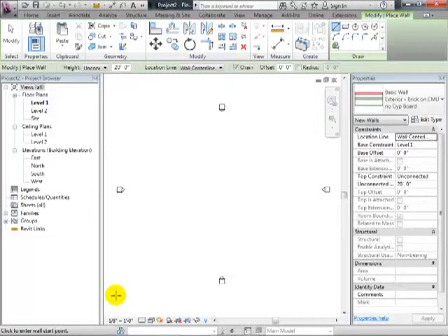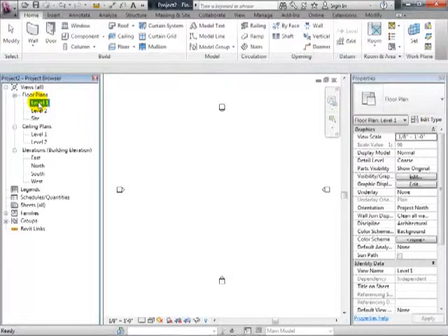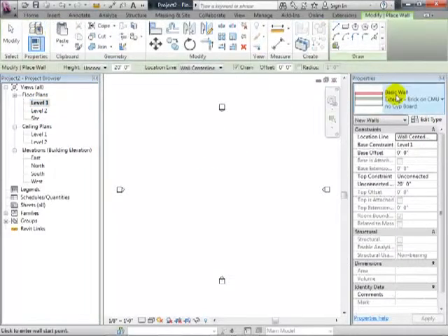Okay, so when you go ahead and put walls in, let's think about just basic wall modeling. If we start placing walls, I'm going to place the wall on level 1, but I'll make it a little bit tall. Choose your basic wall type. You get to say what the height of the wall is, whether it's 20 feet unconnected or up to a specific floor level. Ultimately, you're probably going to do things to specific floor levels. That's really a stronger way to do it. For now, I'm just going to leave it unconnected, because I haven't defined a lot of levels.